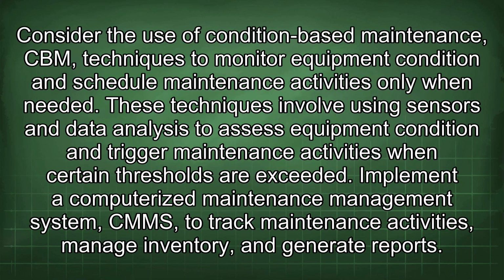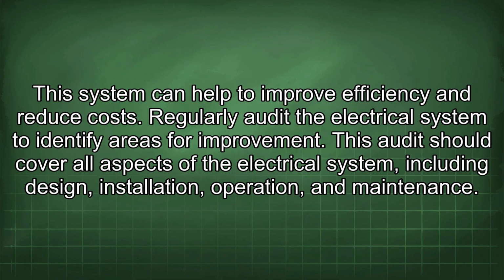Consider the use of condition-based maintenance (CBM) techniques to monitor equipment condition and schedule maintenance activities only when needed. These techniques involve using sensors and data analysis to assess equipment condition and trigger maintenance activities when certain thresholds are exceeded. Implement a computerized maintenance management system (CMMS) to track maintenance activities, manage inventory, and generate reports. This system can help to improve efficiency and reduce costs.